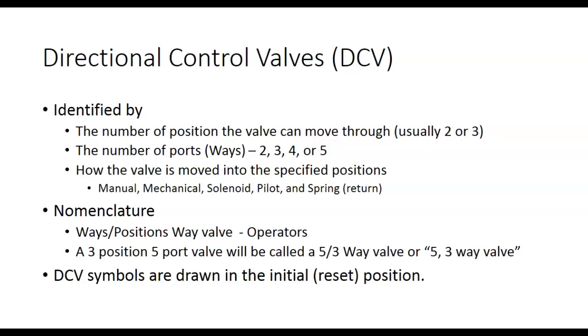They got a little joystick, so they're using solenoid controlled, pilot control. Pilot control means you're using the pressure that you're controlling to move the spool. Then we have solenoid pilot, which you'll see a lot in hydraulics. You deal with 3,000 psi worth of pressure, and you got a directional control valve trying to push the solenoid. The solenoids would be real big.